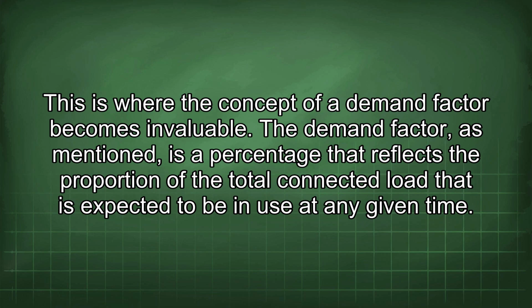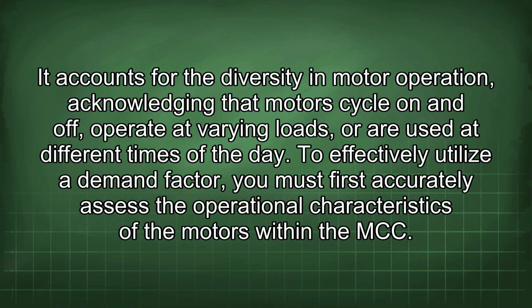The demand factor, as mentioned, is a percentage that reflects the proportion of the total connected load that is expected to be in use at any given time. It accounts for the diversity in motor operation, acknowledging that motors cycle on and off, operate at varying loads, or are used at different times of the day.